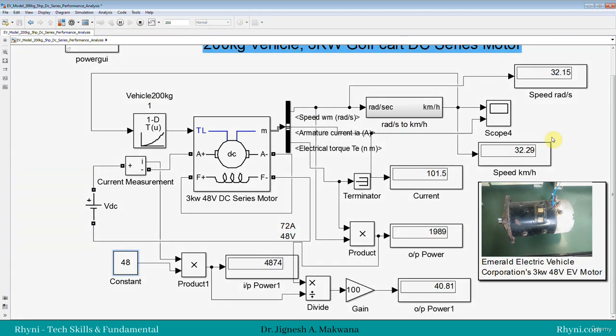So see, this is the maximum voltage we can supply to the motor, and this is the maximum speed that the vehicle can reach on the direct drive, at 63 or 65, more than 65 km per hour. But the thing is that efficiency is low. The first thing we observed is efficiency is more than 60% for rated load, that is 3 kilowatt, right?